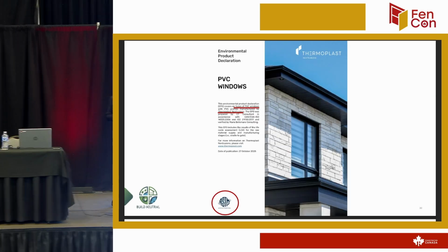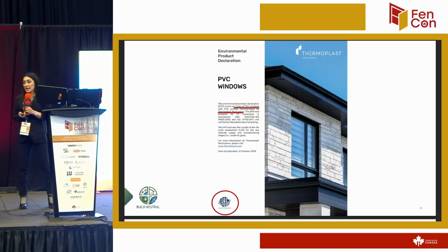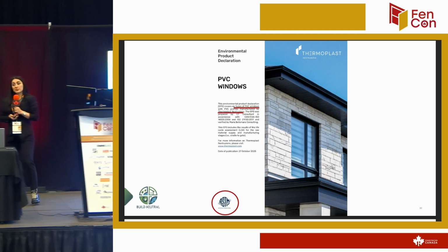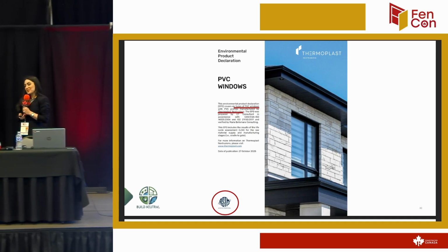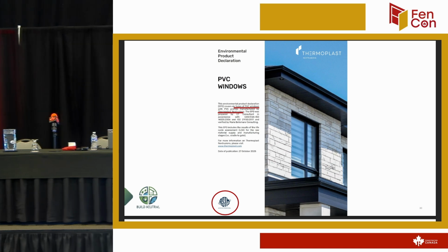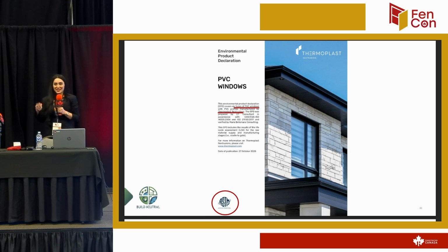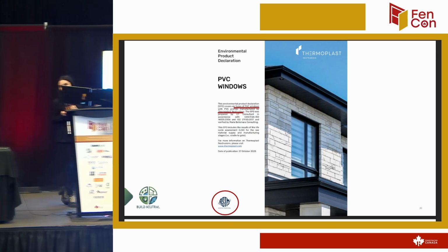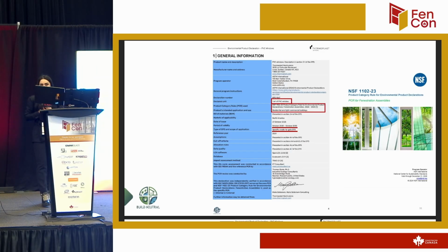So now here we are going to look at some EPDs and see what they have. If you are reading EPDs, it's really important, because some people put EPDs out there, but they just develop them themselves and they're not verified. And sometimes it's hard to distinguish, because the look of it is the same as the look of any other EPD, right? You have to pay attention: does it have a program operator logo? Like here it is ASTM International. Does it have a signature or a name of a verifier? Is it third-party verified, or is it just internally reported?